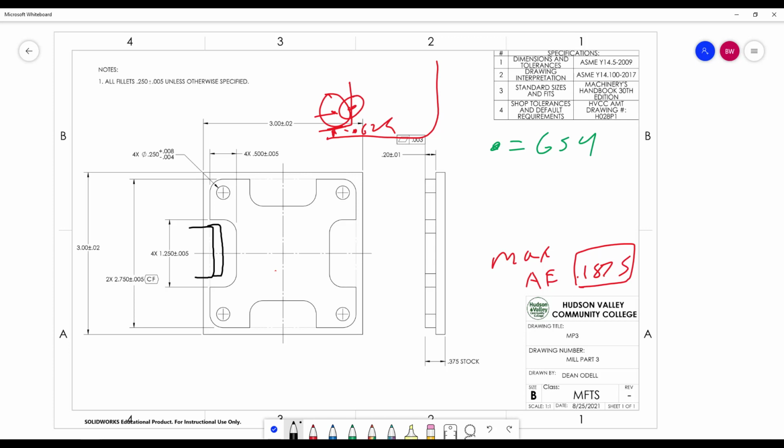So if we went to X minus 1.3125, and we're working from center here, this next line, if we take away a 3/16 depth of cut, 1.3125 minus 0.1875 equals an inch and an eighth, 1.125. That's kind of convenient because that is actually right around here, which is the center of these fillets, or where the center point of the fillets are.